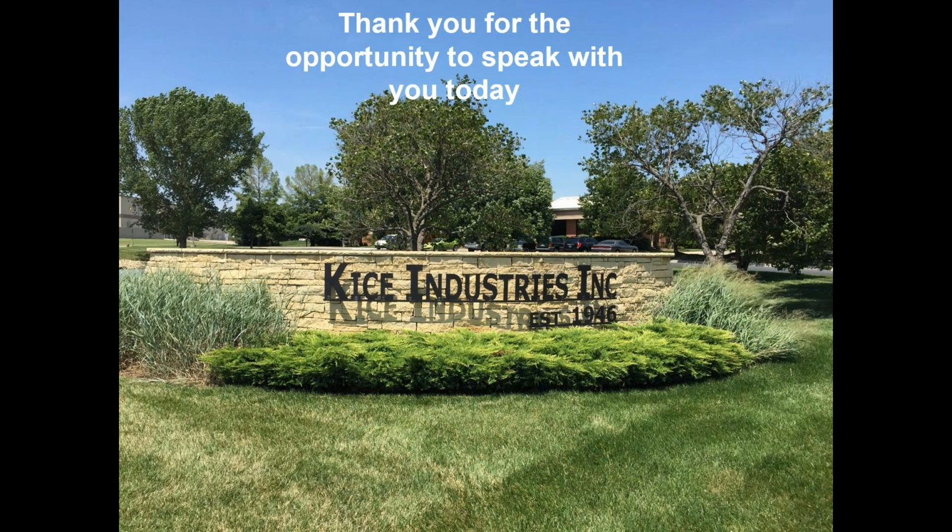You can call us or call whomever you talk to and get yourself a Magnehelic gauge. Get you 50 foot of, I think ours is 1/4 inch airline. Run the line down to the Magnehelic gauge and you're in business. So no, you do not have to climb the ladder every single time to check it if you mount a secondary gauge down at ground level. And of course there are automated versions or electronic versions that can send signals back to a centralized PLC. So if that's something that you want a PLC to be able to read and check on for you, you can do that as well. A little bit fancier, a little bit more cost, but that's also available.